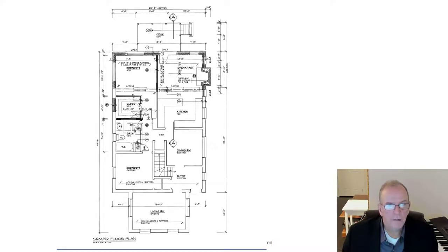And so this addition on the back here, we would have this back wall coming out. So the dashed line would represent the wall that's coming out. 4 2x10s, that's for the roof. Something has to support the roof. So once again, we would have to make sure that we've got the roof supported temporarily when we remove this back wall. That might be a little bit more complicated. Have to look at that a little bit closer to see exactly how that's done. Doesn't show the direction of the joists. The joists are running here too.